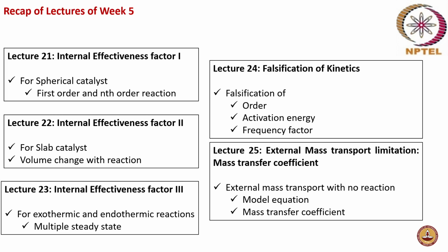In lecture 22, the same internal effectiveness factor was derived for a slab catalyst, and it was observed that the trend of the curve for internal effectiveness factor versus the Thiele modulus remains almost similar across geometries. The internal effectiveness factor accompanied by a volume change was discussed in the same lecture.